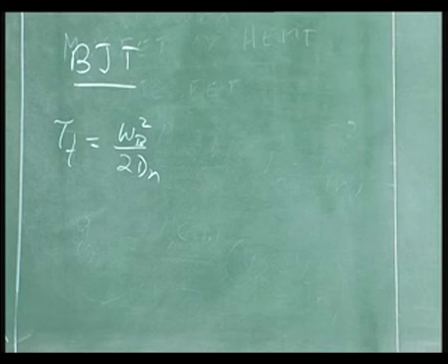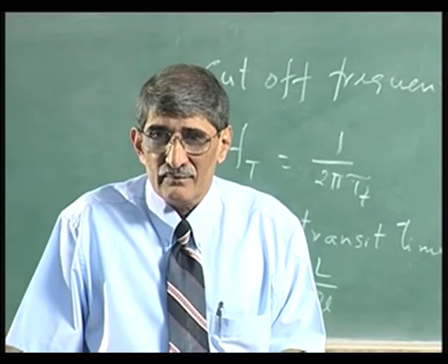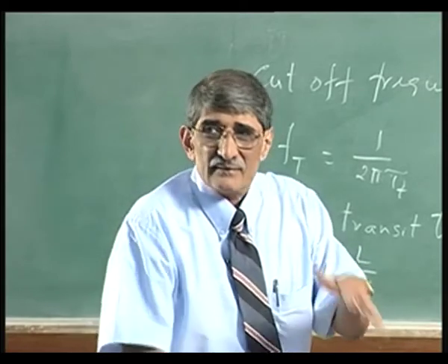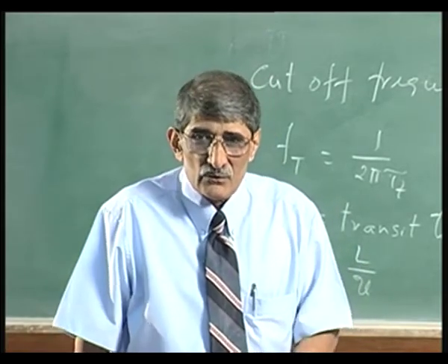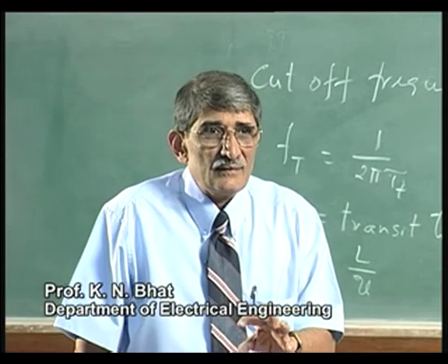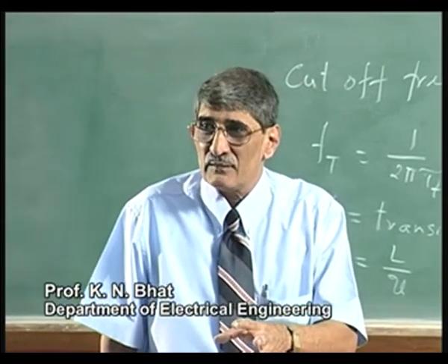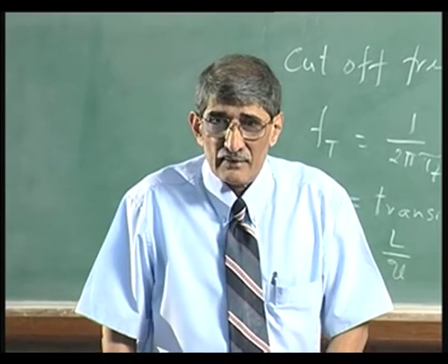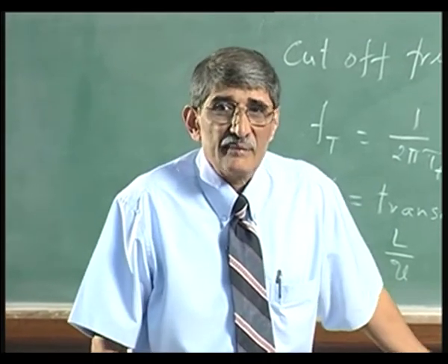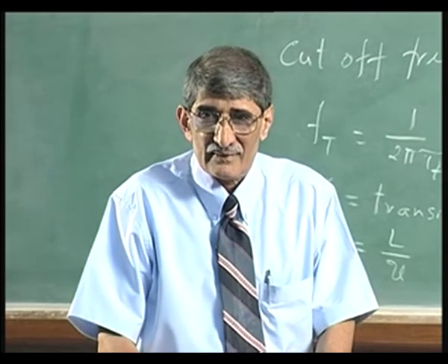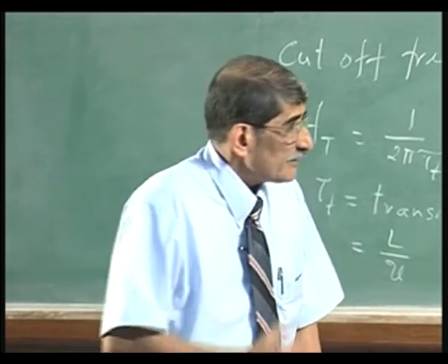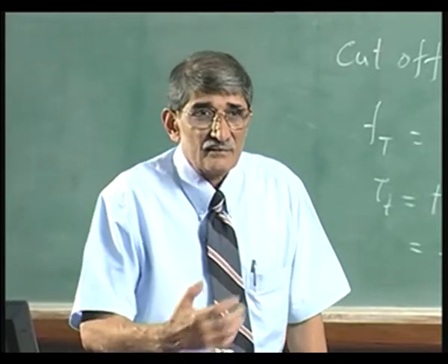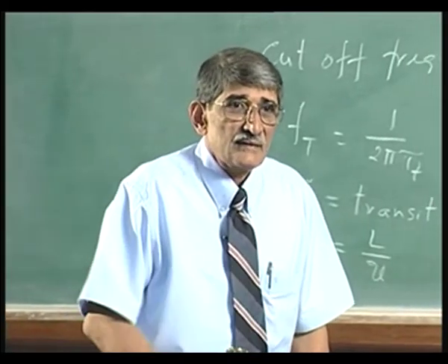Wherever doping concentration variation is there, okay, there is electric field. Wherever there is band gap variation, there is electric field. So, this sort of thing in fact is the trick that they have played in the heterojunction silicon germanium transistor, where you do not have to vary doping, you can vary the band gap to bring in the electric field. Okay. I think it will be very interesting to see some of those silicon germanium concepts in this discussion itself.